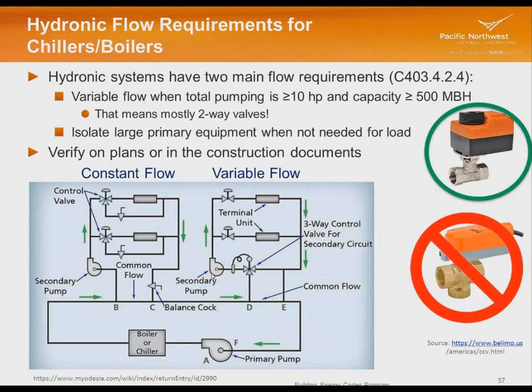But even without that, even if a variable speed drive was not required on the pump, if we use these valves to throttle back, that pump will ride the pump curve and we will get some significant savings. Now we do have one three-way valve in this system. You might see that. That is to provide the temperature, and we'll talk about temperature reset in a minute, going out to the system, because maybe our boiler needs to operate at a high temperature, but we don't need high temperature out in the system itself. So that's what's going on.